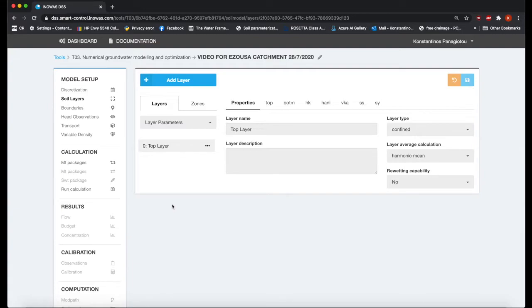So here we need to define the top elevation of the layer, the bottom elevation of the layer, and the horizontal conductivity, which has 2 directions. Let's say the XY plane, if this plane is assumed to be the horizontal plane, then we need to define both an X and Y component for the conductivity.